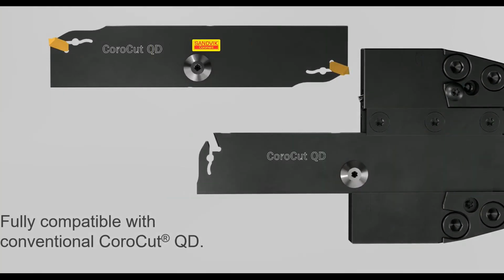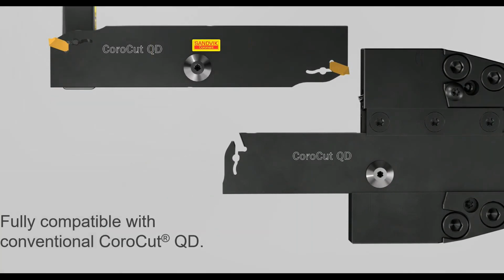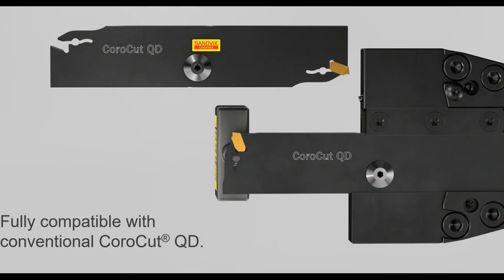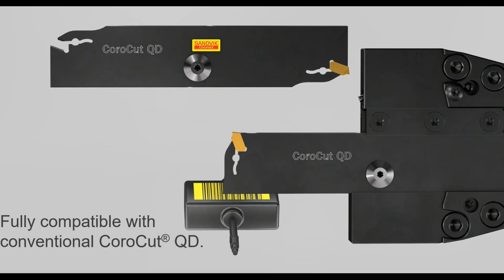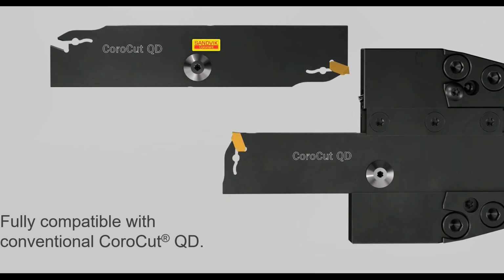So again, here it's the same tool holder, just a different blade and the same insert. And you can see the top of the y-axis blade that's in the tool block actually has a flat on the top. So that is one area that you will touch off using your probe. And then you'll actually touch off the front of the insert. And then the offsets are laser marked onto the holder so you can put in the correct offsets for that blade.